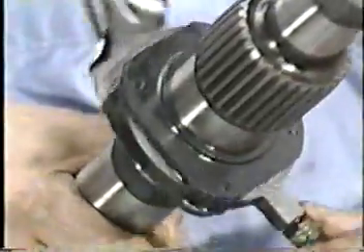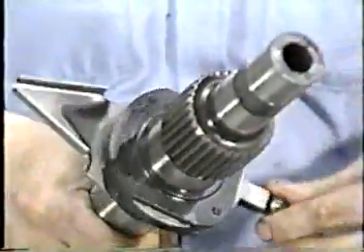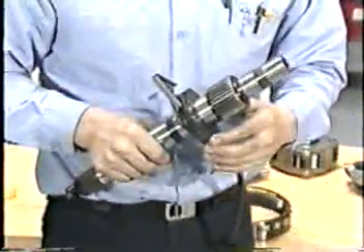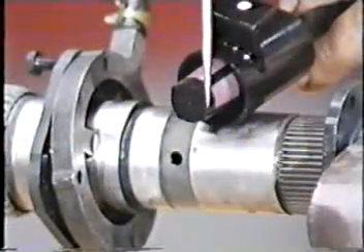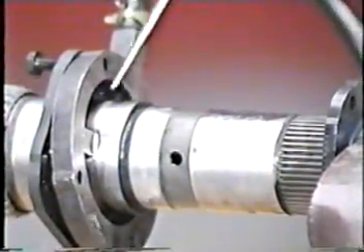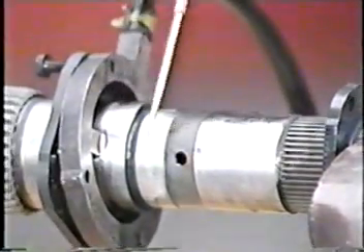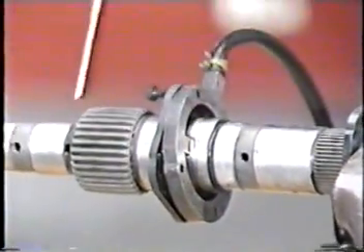Check the rear output shaft and oil pump. The output shaft powers the drive shaft to the rear wheels. The oil pump and chain lubricate the transfer case components. Check the strainer and oil holes for clogging. Check the oil pump body, spring pins, and the shaft splines for wear or damage.